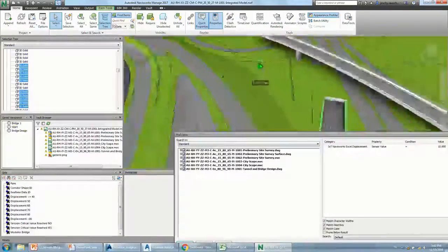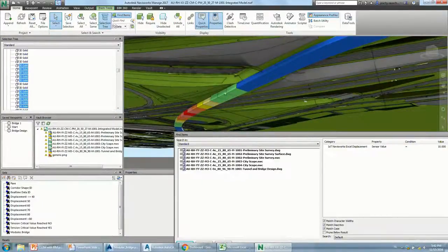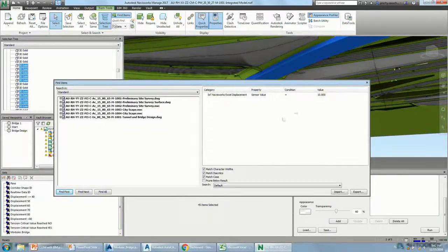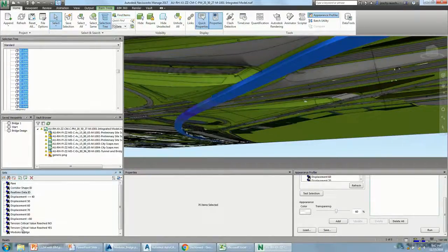And if we go below, you can see it actually selected all of these. So we're going to save this as a search set, not a selection set, because if we add some stuff with the same value, it searches for that as well. If we would do a selection set, it's just a relatively stupid selection. So if we have that in place, we can do this for all the objects.